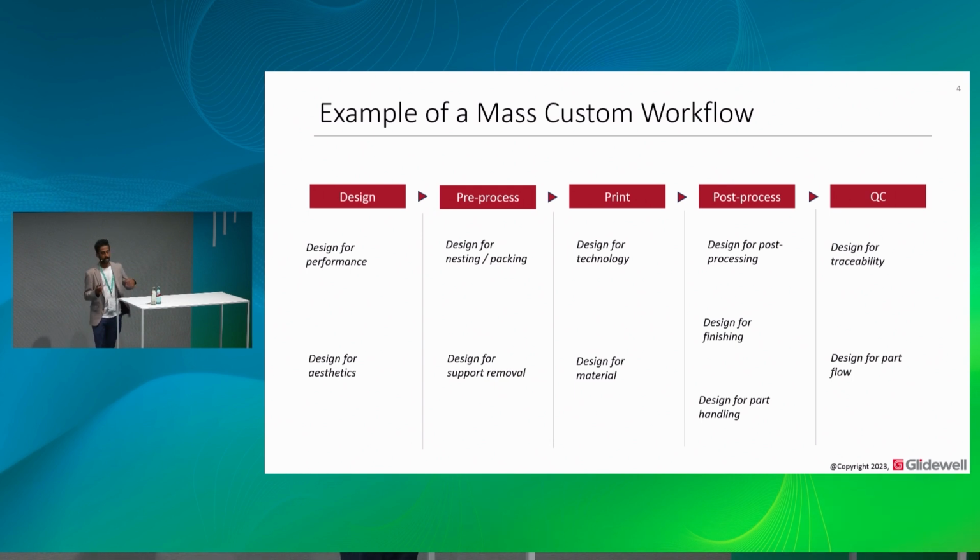For example, if you had a specific type of jig or fixture that was moving these parts from one machine to the other, then making sure that each of these parts can interface with that fixture in a structured way, but also in a repeatable way, automatically streamlines your process and also reduces labor time.